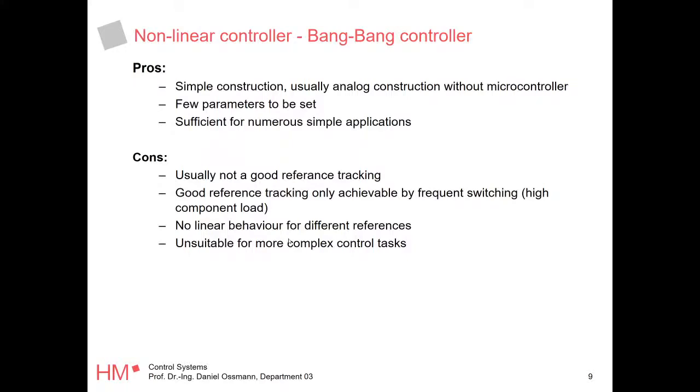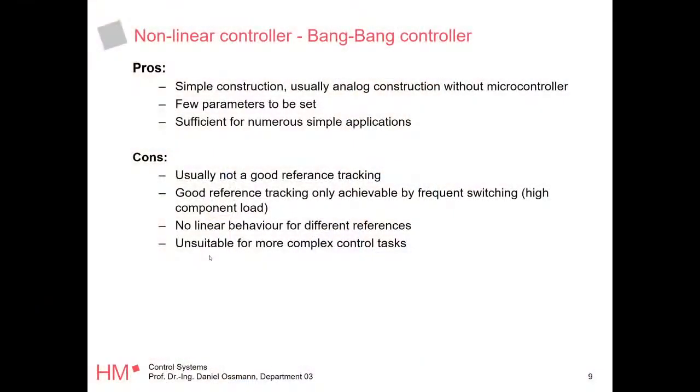The system is unfortunately non-linear, right? So what does that mean here? It will behave differently for different inputs. For a linear system, if I go in with a value of 5 and my output is 10, I know if I go in with 10, my output is going to be 20. So there's a linear dependency. While for a nonlinear system like this bang bang controller, I don't have this dependency. So it's really hard to work with this system if you do have very hard constraints in your design. So basically what I'm trying to say, it's unsuitable for a complex control task.